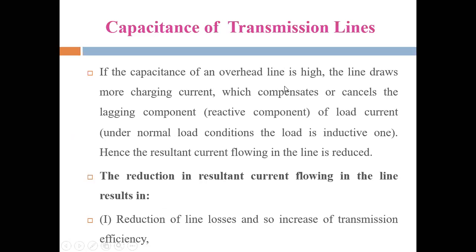If the capacitance of an overhead line is high, that line draws more charging current, since IC depends upon the capacitance. So when the capacitance value increases, IC also increases without increasing the voltage.